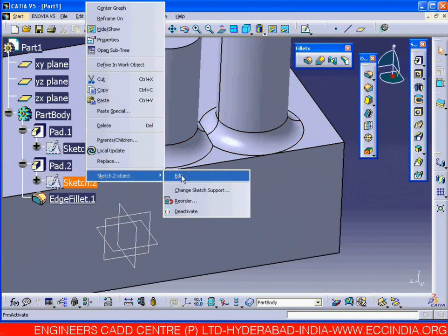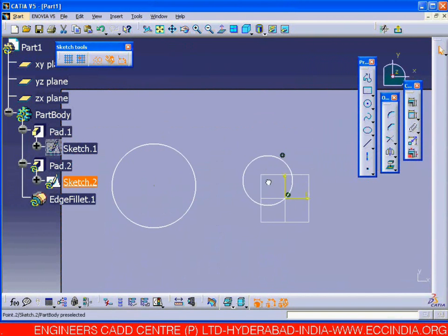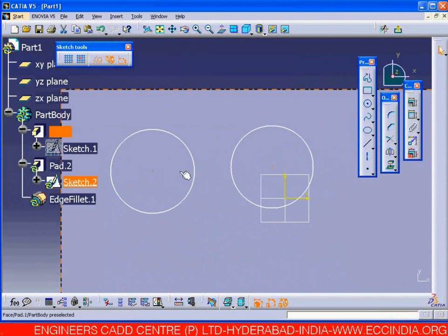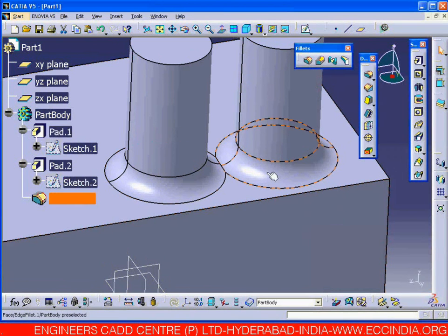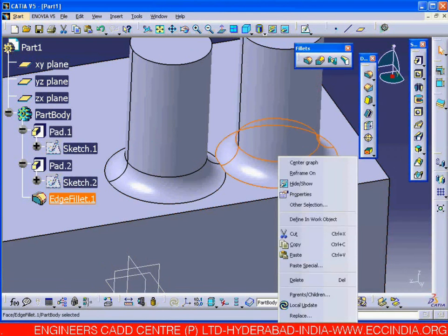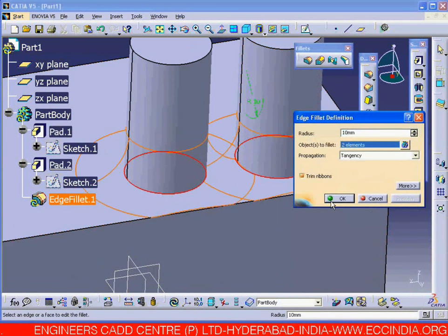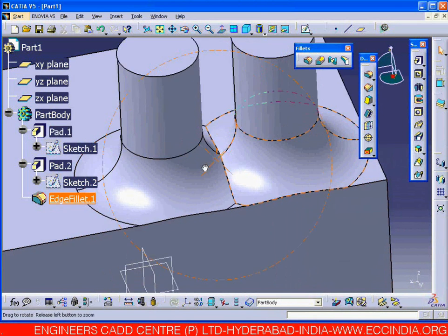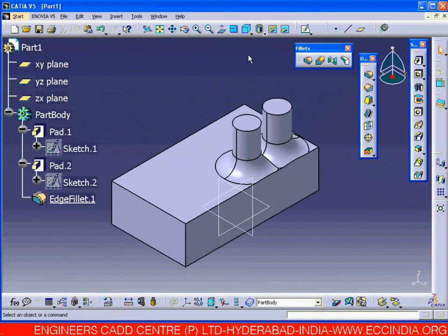Okay, small changes again in this parent. More dragging outside. Drag it. Now once again you can perform the redefine. Fillet I'm making as some 10. Right. The fillet material is here, it is trimmed, and the fillet has taken place. Now see this object in right side view.